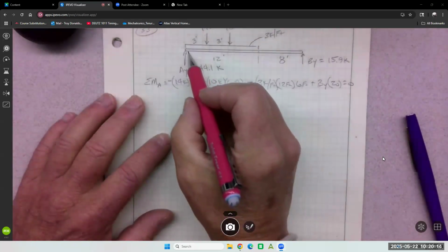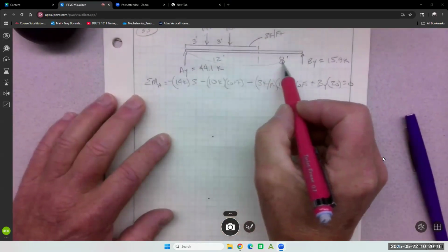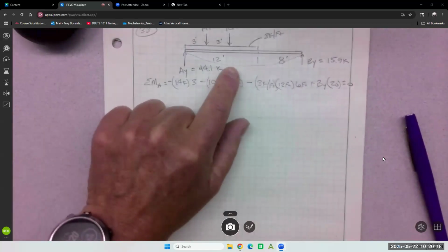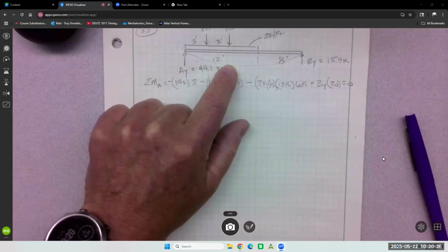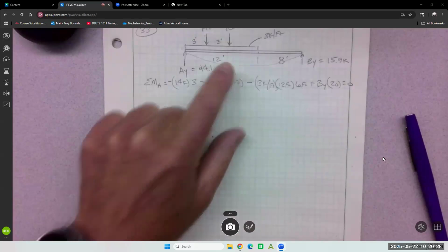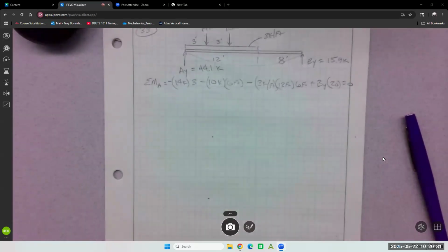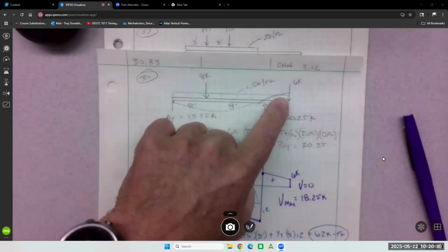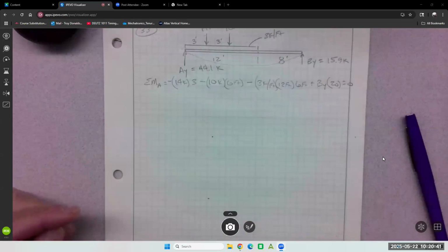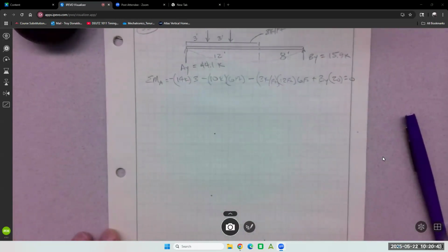This one, the deflection curve would just be like this, all concave up, right? If it deflected, that means the moment's going to be entirely positive. So that's a clue. But once you start to pick up this deflection thing, it tells you, oh, this moment is all positive. Where this one tells me, oh, this moment is both positive and negative. So that's helpful.